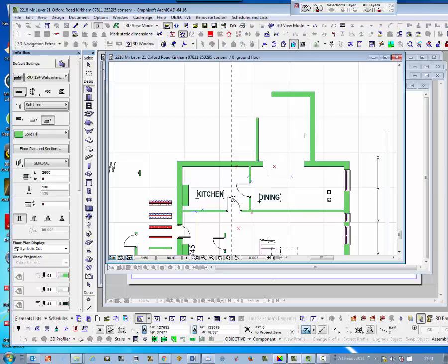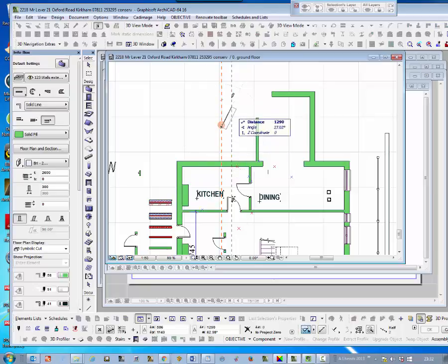Now then, the other outside wall from this one here, from my survey notes, is 1990. So I want the parameters of that, so I alt click on it, place the cursor on the side of that wall, press X, because I'm going in the X direction, 1990, in the minus direction, enter. As you can see, depending which way you go, the reference line will be up or down.